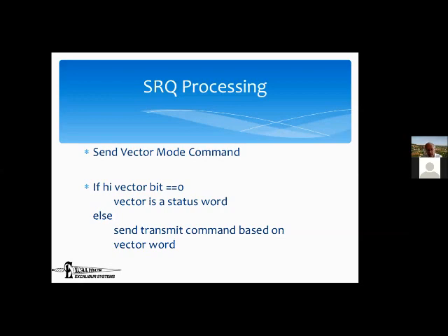And really, we could have done this by just having the bus controller once a second ask, are you on fire? But given the number of possible things that could go wrong and all the different RTs, this is a much better mechanism, because it costs 0 time if nothing goes wrong and doesn't cost a lot of time if something does go wrong. So it's much, much more efficient than just polling for problems.